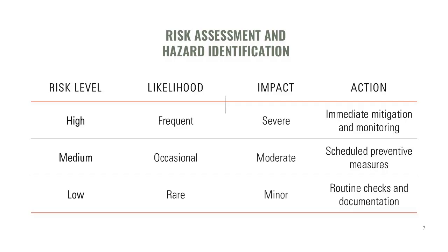Risk assessment is a systematic process for identifying hazards, evaluating their likelihood and consequences, and implementing controls. Techniques include qualitative methods like HAZOP, hazard and operability study, and quantitative approaches such as probabilistic risk analysis. Key factors considered are pipeline age, material properties, operating conditions, and environmental sensitivity.